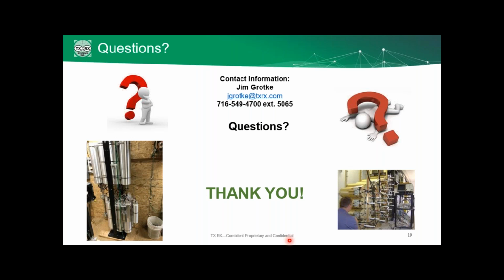We ask for any information if it's an existing design. We ask for the frequency information and the frequency plan, antenna information, antenna separation information, and mounting information. All of that is extremely important, because if we have to keep going back to try to get more information, then it slows down our design process.